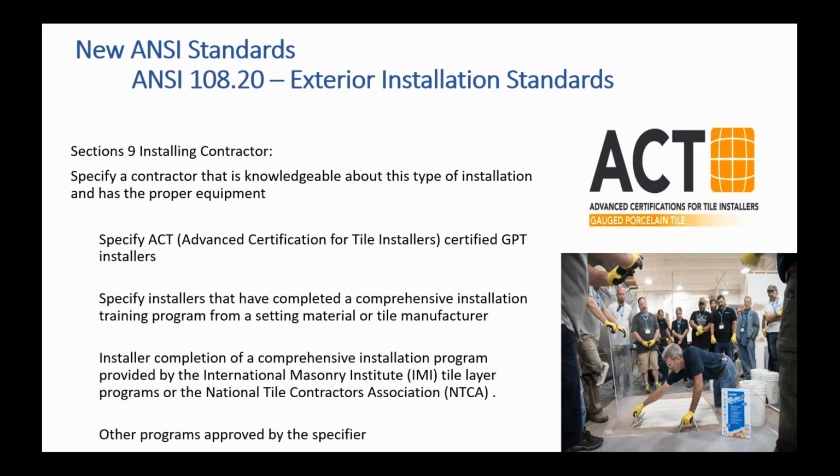The installing contractor, we recommend qualified labor in the standard. That means that the installers had training on gauge porcelain tile. We do them here. I know some tile manufacturers do it. What the standard says is that contractors should have knowledge of this type of installation and have the proper equipment. They can go to ACT, CTEF, and take an advanced certification tile installer course for gauge porcelain tile. This is the standard or the class right here.